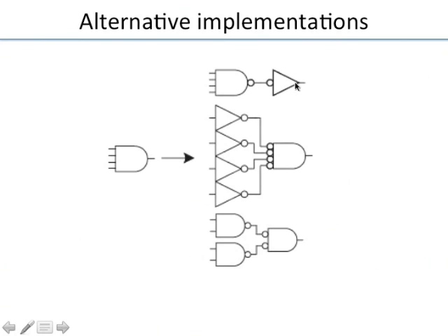If you notice out here, it's a funny style of writing the inverter, right? So the inverter is a triangle, but the bubble, instead of being at the output, has been put at the input. Why? Just so that when you read it, it becomes very clear, because these two bubbles will cancel each other. So you know it's just an AND followed by a buffer, so it's an AND gate. So just for readability, for you to quickly see what the function is, this is done. Similarly out here, this bubble will cancel this bubble, so it's implementing the same logic functionality.